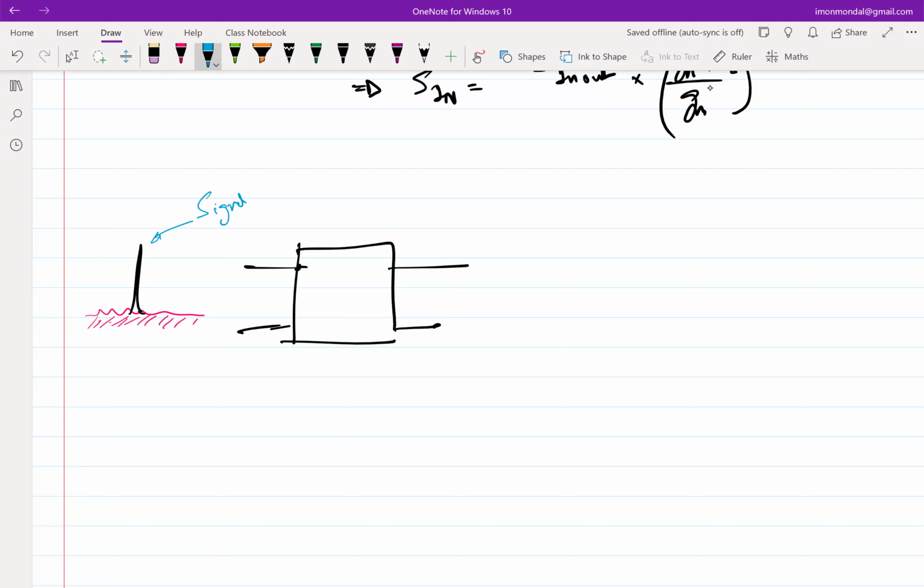Or if I just say the power is P in. It will typically give you readings in terms of dBm. So whatever dBm you get, right? What about noise? How do you know what is the noise strength? Yeah, noise floor times bandwidth, right? So whatever you get here is typically in dBm. This guy is in dBm per hertz, because this is power spectral density, right? Power per hertz, power you can express in dBm divided by hertz.